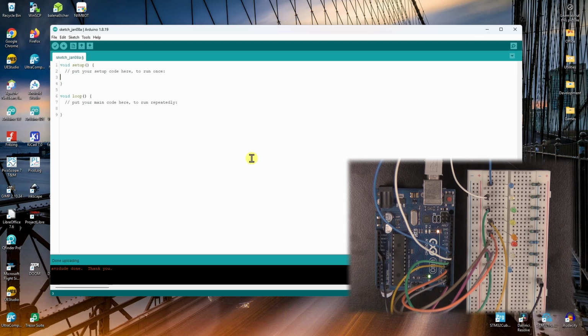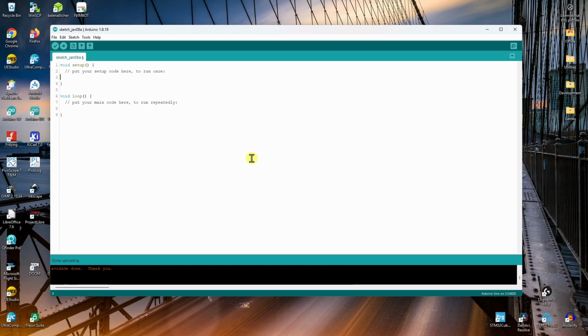I'll use this Uno, which has got these LEDs attached, which I won't be using just yet, but we'll be using them shortly when we start sending some commands to it. And you've probably seen this before. It's fairly standard in most programs. There'll be a Serial.begin, then some number. A lot of them will use 9600, and I'll come back and visit that shortly. And you've also probably seen this, which just prints a message.